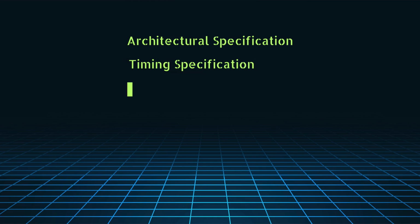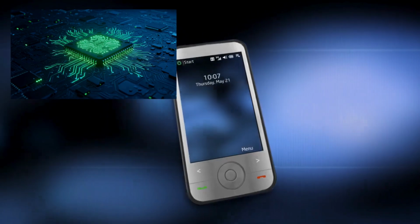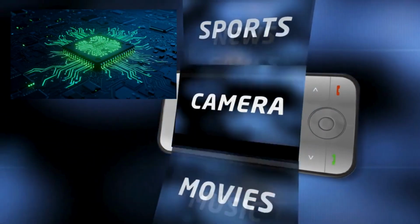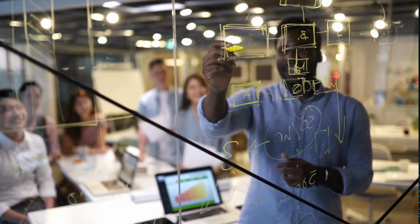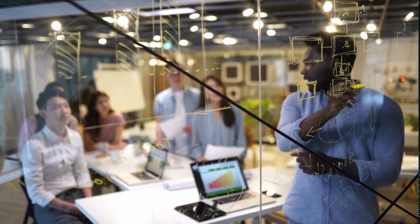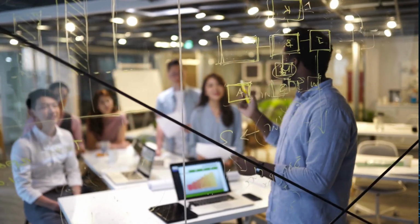The first step for any verification engineer is to have a specification, so that he can know what features are inside that chip, and he will write test cases for those specific features. Now the second step: if he knows the features, then he has to make a verification plan for them, how he will verify each feature and how many test cases and scenarios he will write for it.